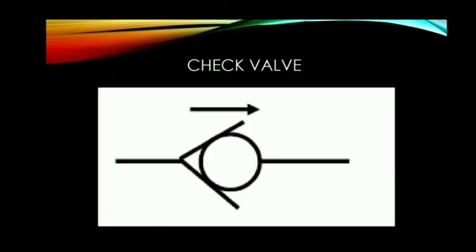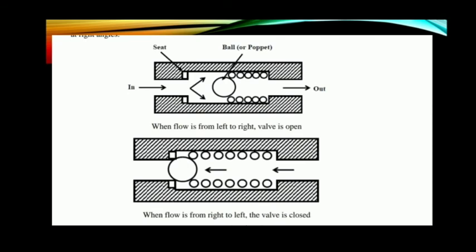Directional control valves. In directional control valves, it is basically the directions of the flows that are controlled and not the magnitudes. Directional valves can be characterized depending on the number of ports, the number of directions of flow that can be established, the number of positions of the valve, etc. They are mainly classified in terms of the number of flow directions, such as one-way, two-way or four-way valves. Directional valves are often operated in selected modes using hydraulic pressure from remote locations. Such mechanisms are known as pilots.